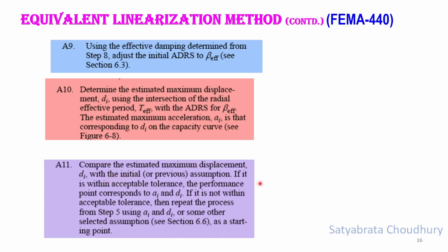Step 11, compare the estimated maximum displacement di with the initial value which was written as dpi. If the performance points are close to each other, then you can stop, or you can further carry on the iteration. We have discussed this in a previous video also.